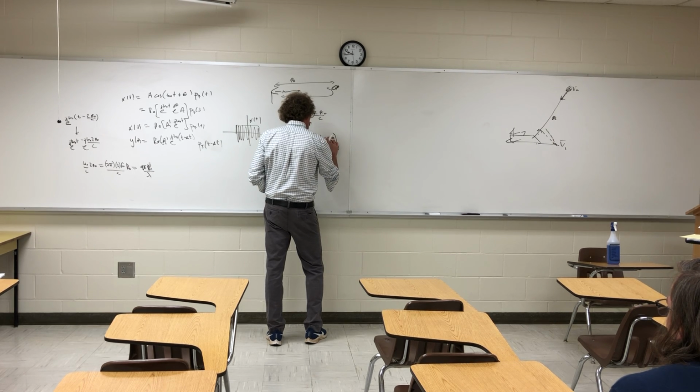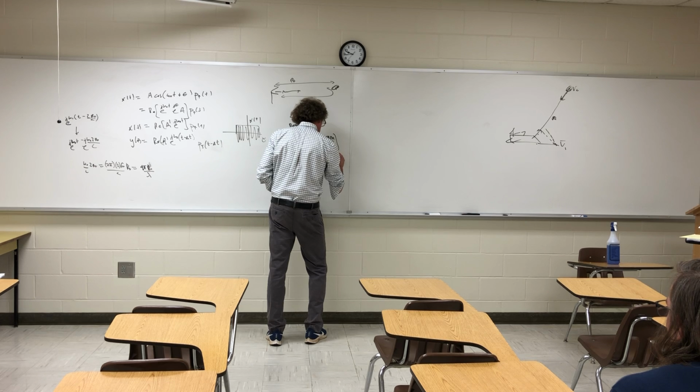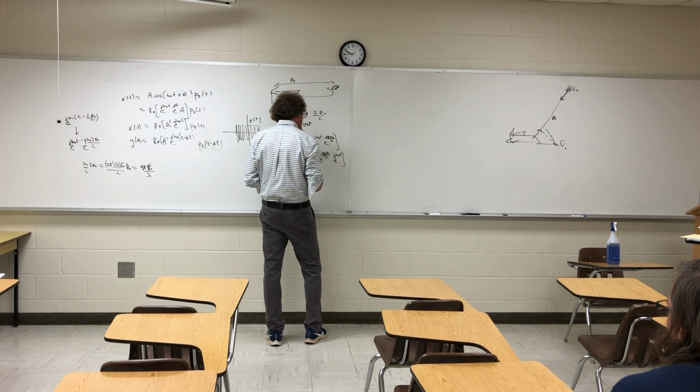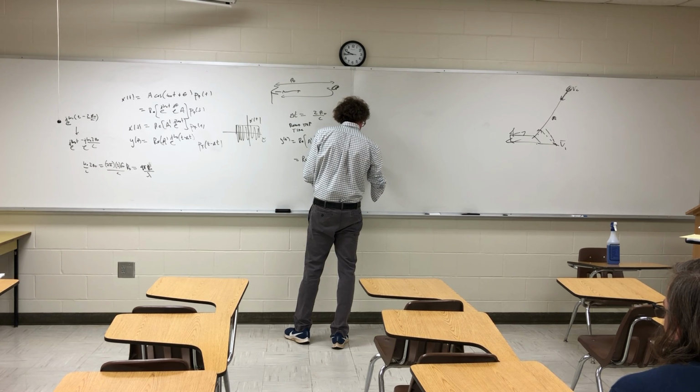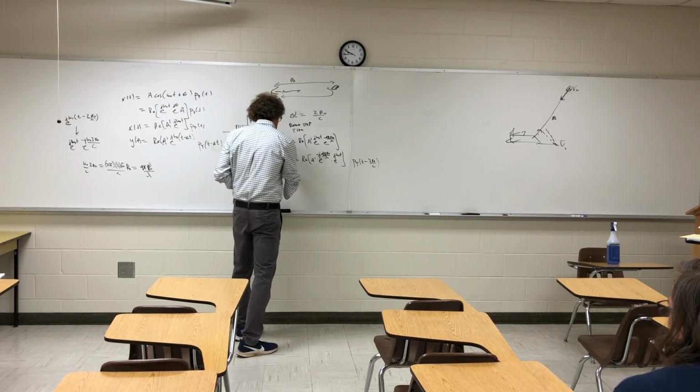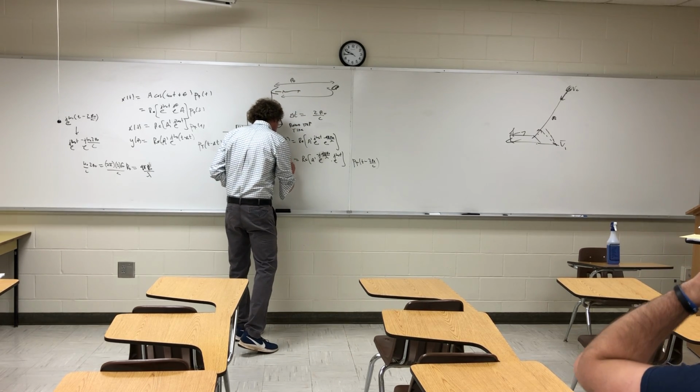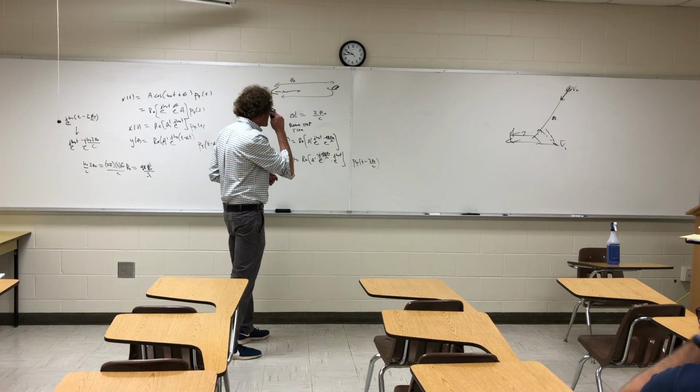Or I'm sorry, this is 4 pi. 4 pi r naught over the wavelength times e to the j omega naught t. And it's also times the pulse, p tau, of t minus 2 r naught over c. And that's y2. And that's the return signal.